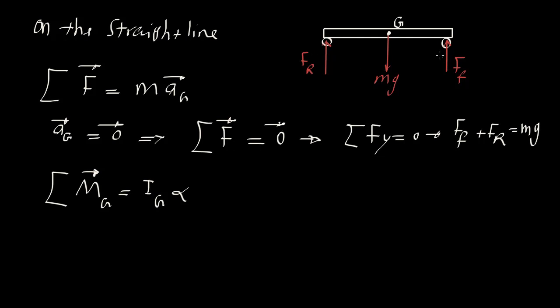And again, because this skateboard is just moving to the right without any acceleration and any rotation, alpha here is 0. We said that we don't use the vector notation here because we are in 2D, everything for the Euler equation is in the k direction, normal to the plane. So here the alpha is equal to 0, so this is equal to 0, therefore this is 0, and now we can sum up all the moments due to these forces.